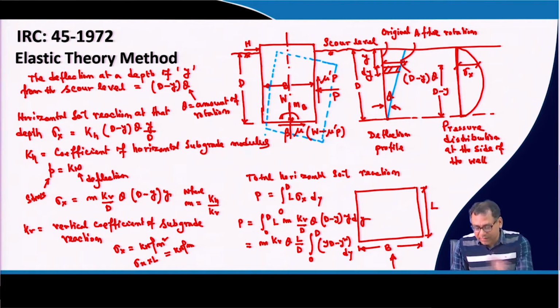Or I should say, the direction of the applied moment is clockwise, and the other moments are in the anti-clockwise direction. We are taking the moment from the base. The moment due to W, which is acting at the CG, and the moment from the origin, where the origin itself is the CG of the well, and the moment acting at the base of the well, we will not consider, because we are taking moments from the base.